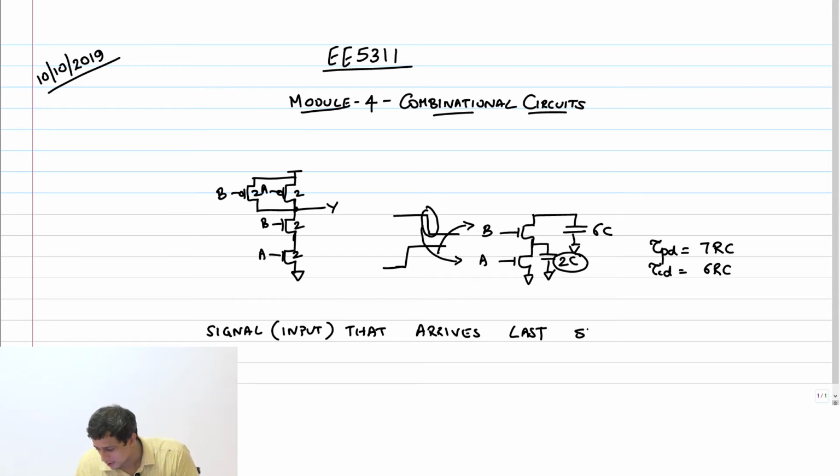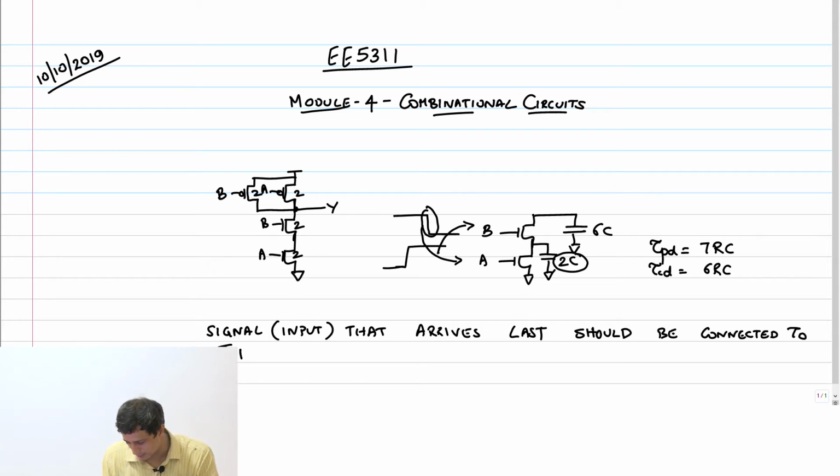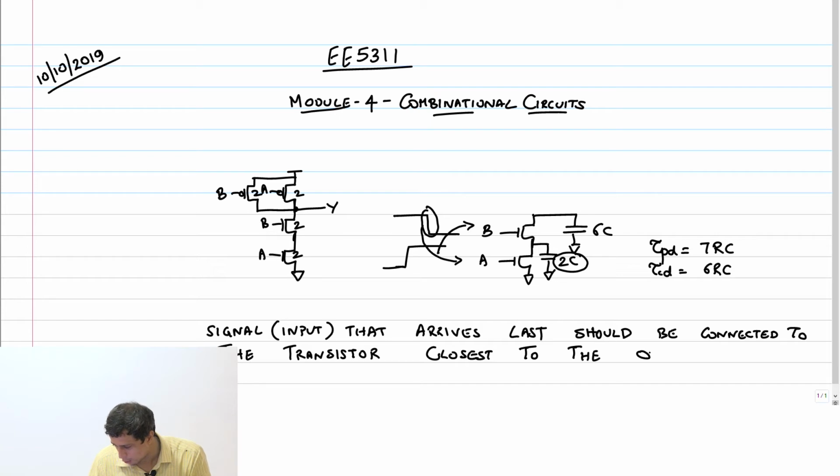The input that arrives last should be connected to the transistor closest to the output.